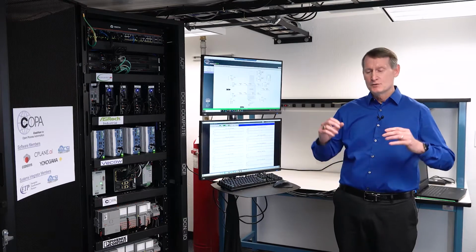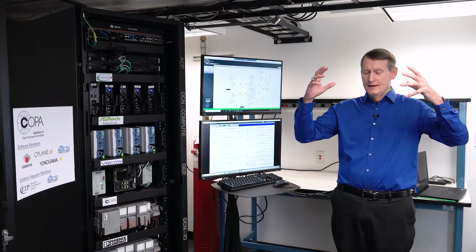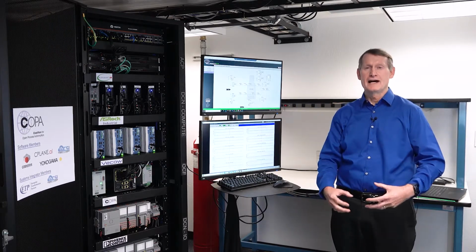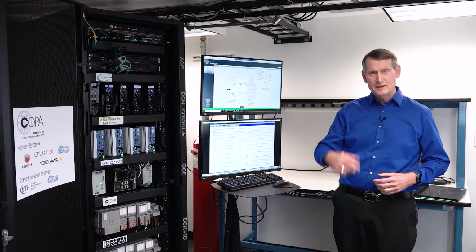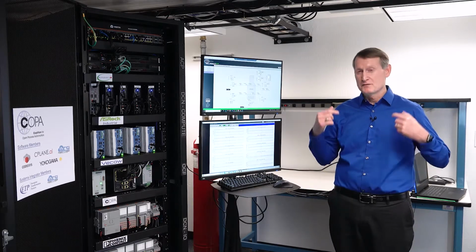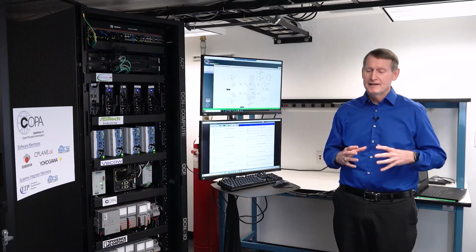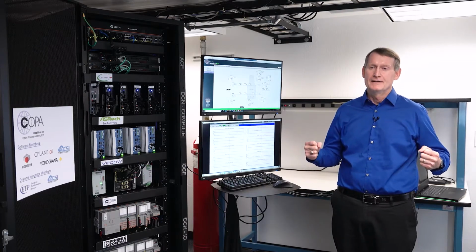The problem is that you have to run this technology way up at the top in a separate computer, and the DCS actually blocks your path down to the I/O. And so as you're doing communication between the MPC and the I/O, you're using outdated communication protocols. The bandwidth isn't what you need. And the result is that you can't run as fast as you would like to, and you can't have the large scope of problem that you would like to. All right, so that's very frustrating.